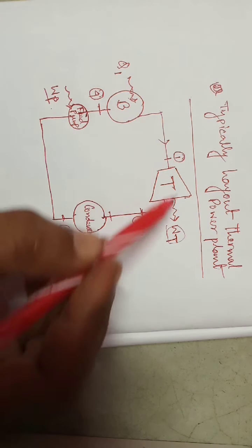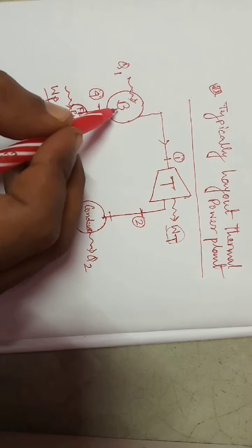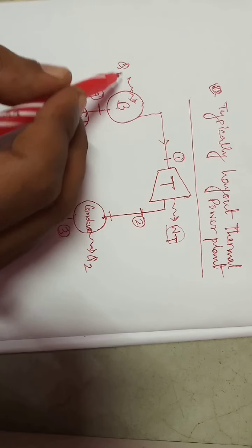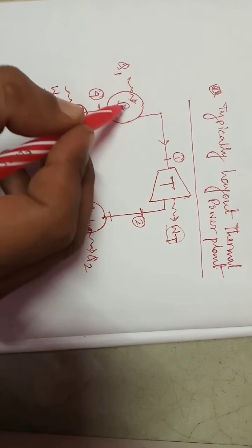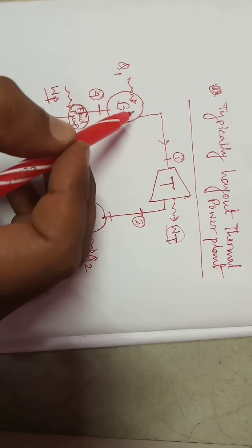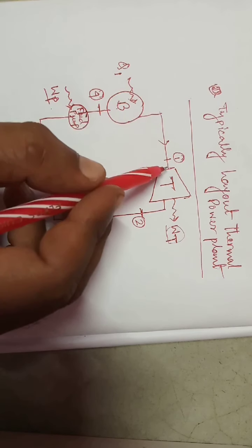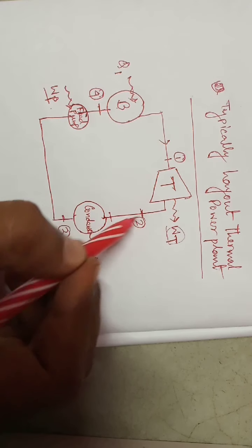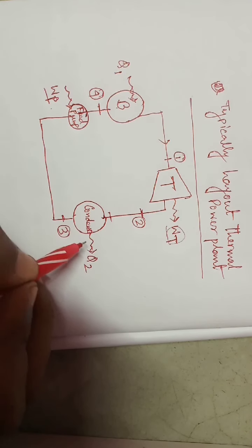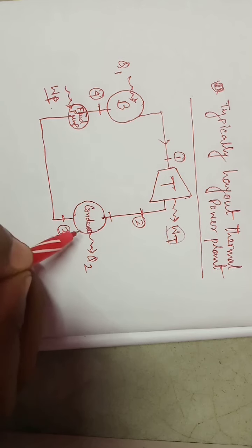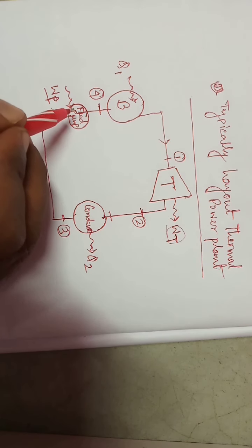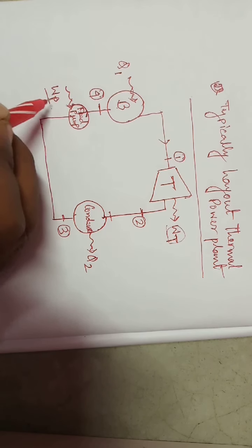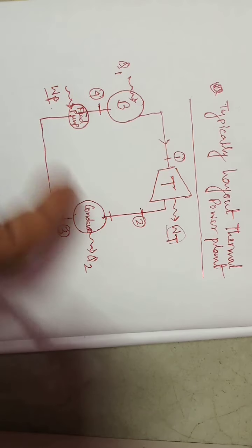So this cycle repeats. There is a water molecule which gets heated and ultimately we can say it is superheated and comes into the turbine, which produces shaft work, and it goes into the condenser, where it rejects an amount of heat Q2, and ultimately in a feed pump it takes WP amount of work, and this cycle rotates.